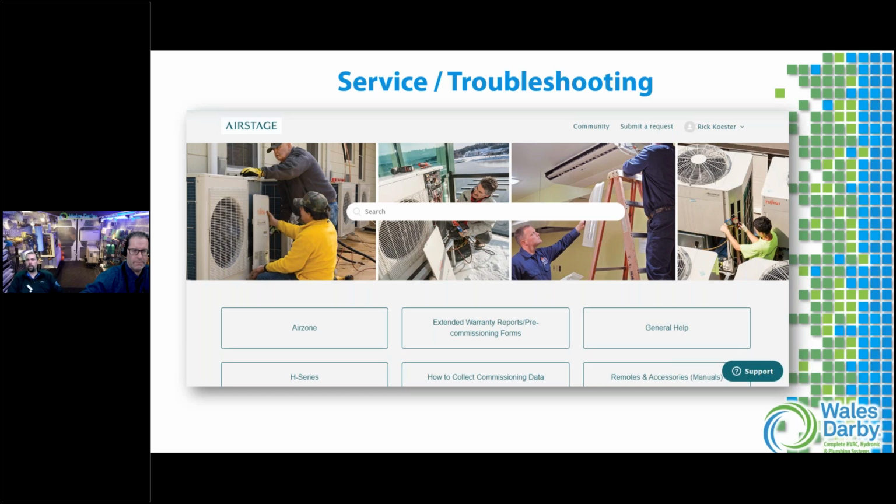The main differences between J and H, we'll just cover it quick, is the H series, we power everything from our outdoor unit as far as indoor units go, right? H series, our expansion valves are in the outdoor unit. When we switch over to the J series, we do things a little differently. There's some increased cost there because now we're powering our indoor unit heads separately, on a separate breaker than our outdoor unit. We tie in all of our indoor and outdoor units by a LonWorks cable. It's a communication cable that we daisy chain. So a little bit more on the labor side, maybe not feasible on every residential application. That's why we see it a lot more commercially.